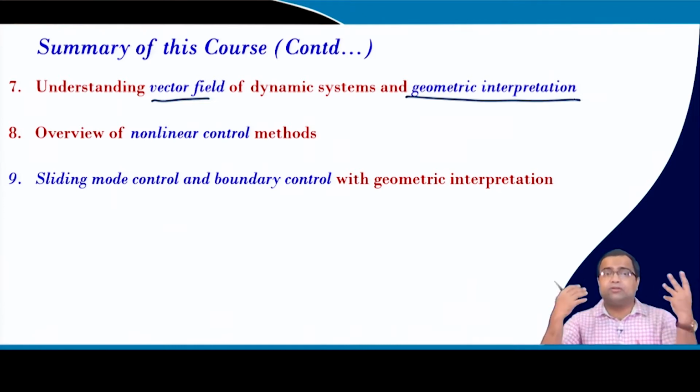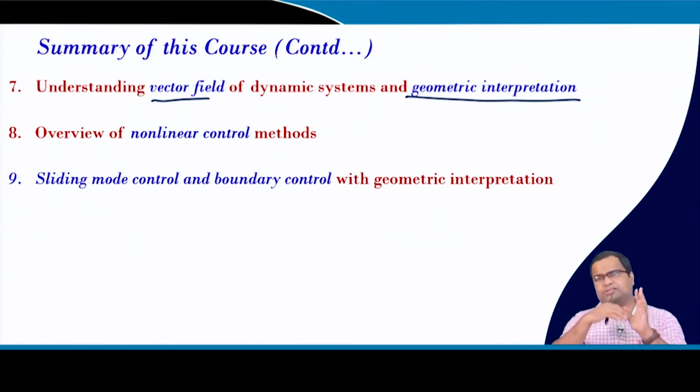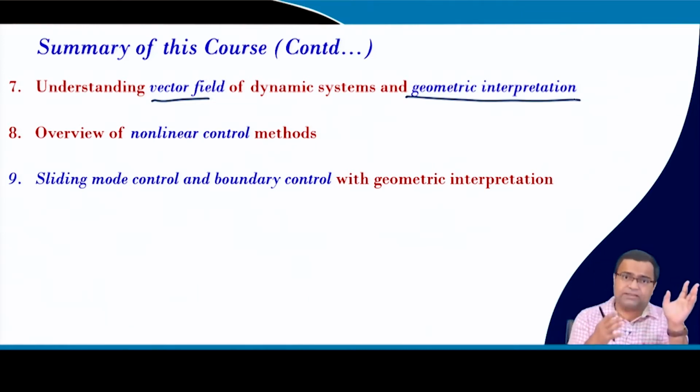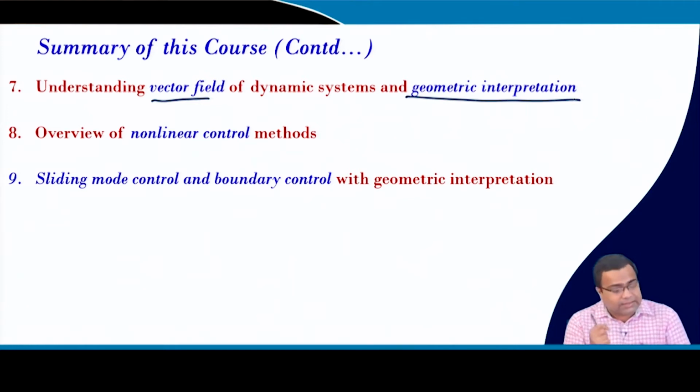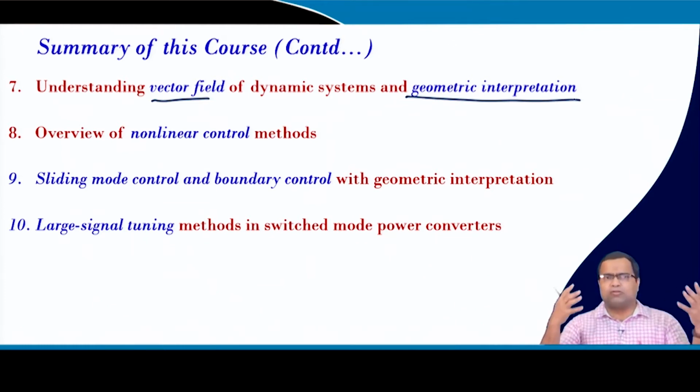That is the concept of boundary control, where we try to shape the switching surface in such a way that it becomes the desired trajectory, right. But there we found that higher order switching surfaces have a complex implementation architecture because of the squaring block and other blocks.